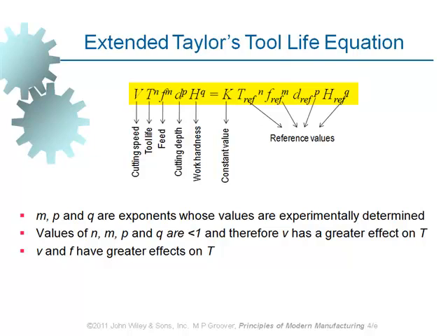There are so many people doing research on machining operations, trying to introduce more useful equations relating cutting speed to tool life. However, Taylor's equation has been the most well-known and widely used equation since then, because it is very easy to use. By the way, it provides a very good, useful relationship between cutting speed and tool life.